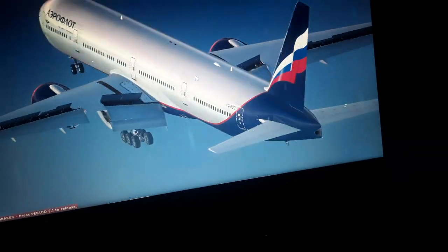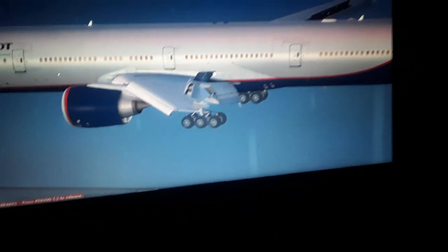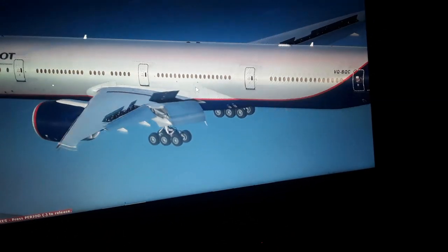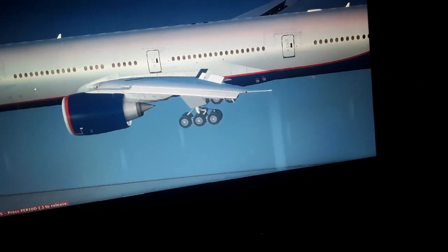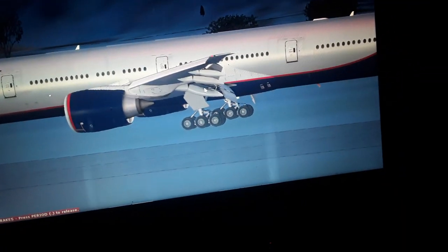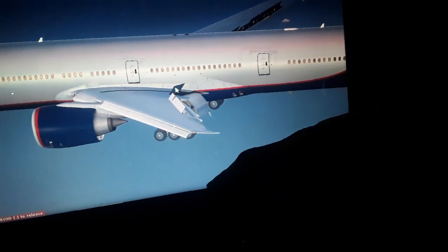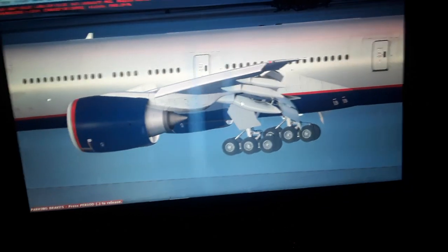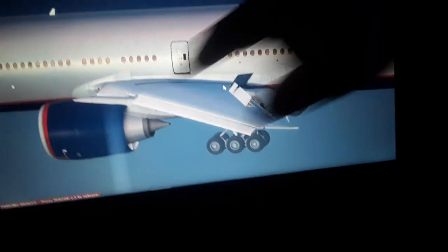And we increase the wing surface area using all the flaps and the slats extended. You can also use flight spoilers in flight. You can extend them to decrease the lift of the aircraft. So as you move forward, you have this airstream of air coming from the front of the wing, from the leading edge all the way back to the trailing edge. So you have the bottom surface of the wings. You can see it's more flat, while the top surface of the wing is more curved.